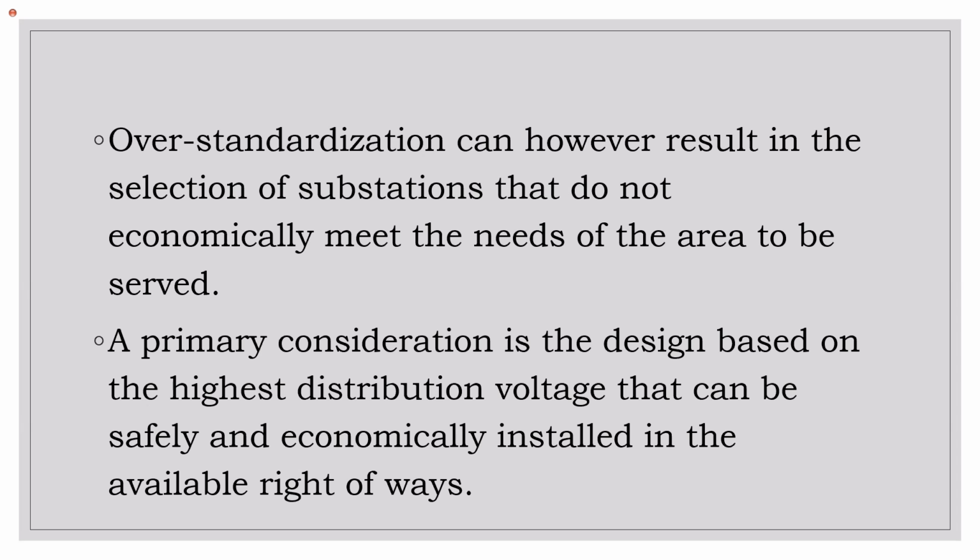Now, one primary consideration is based on the distribution voltage. Remember, we said that voltage, and I had it at the top there. Voltage is one of the key factors in deciding on the layout of your substation. Right? And the highest distribution voltage that can be safely and economically installed in the available right of ways.